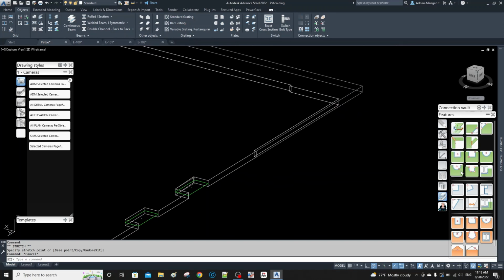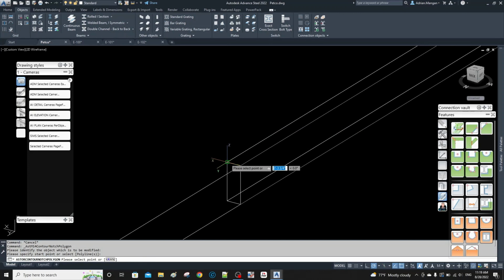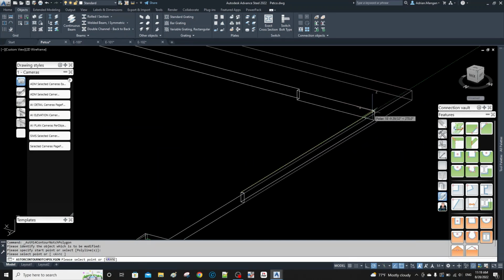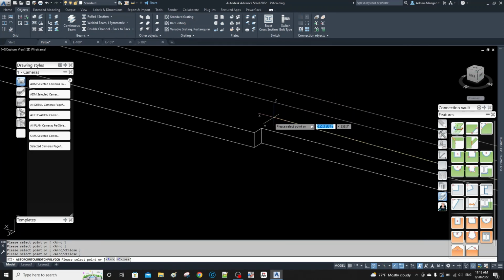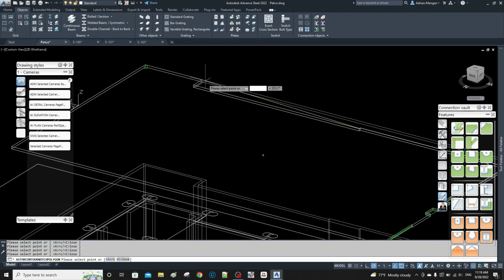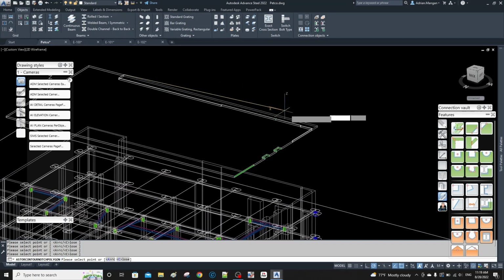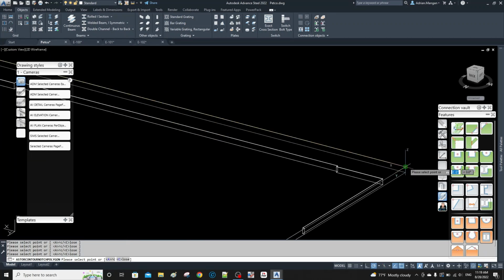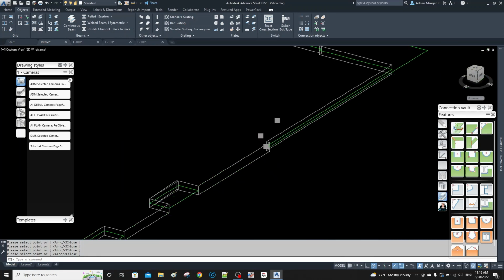Alright, so now we can also do a polygon feature on this if we want. We could just trace around the slab that's already there, or we could have the polygon already there, whatever you choose. You can right click and choose polygon. Some people feel like it's time consuming, but it's nice to get your jobs done right too, right? Back to the start point, and there's your feature, okay?